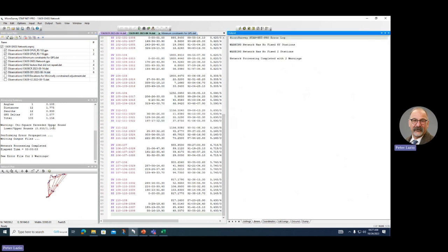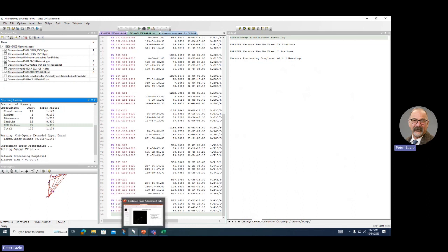And so now this passes the chi-square test. The distances, the angles, well, there's only one angle involved in there. You still have your 7 OPUS RS, 12 different distances, and your GPS, and this passes. So that's now combining the OPUS RS, the GPS, and the total station, which is what we've done basically up to this point on much simpler examples.